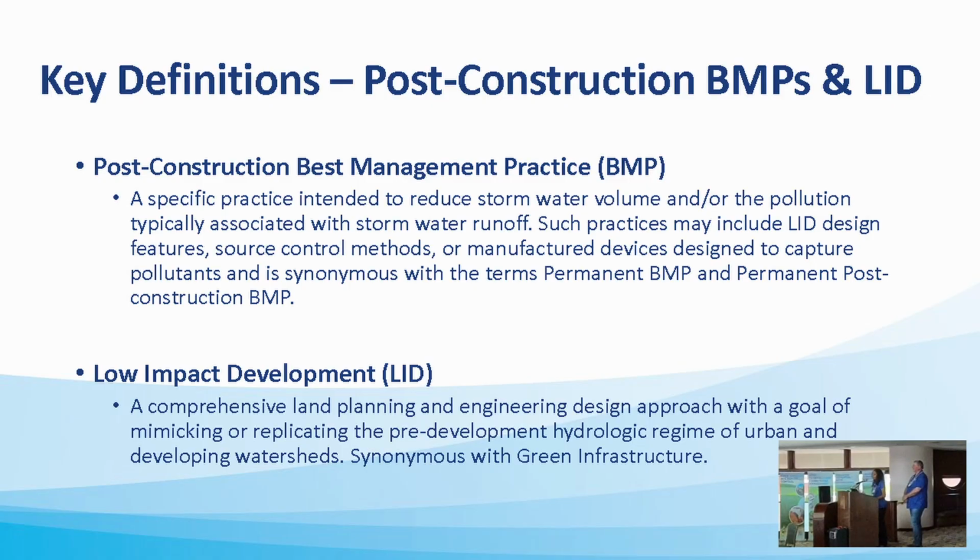And what is low impact development? Low impact development is a land planning and design approach with the goal of mimicking pre-development hydrology. So if you're going into a project and you're going to include impervious surface, you're trying to have the same amount of water discharging post-construction as before construction. So that's the goal. And then EPA has been using green infrastructure as a synonymous word for LID.